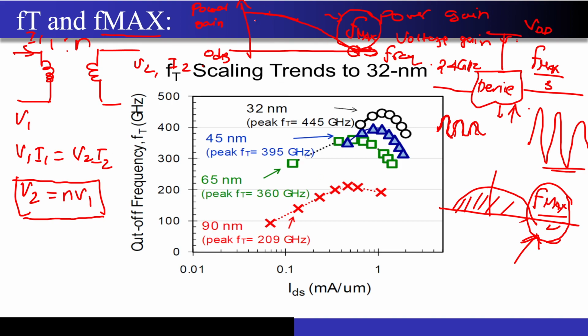Power gain, we usually want a very high number, right? For example, if I get 30 dB of power gain from this device, that is even better, because I can get a lot of swing from here, correct? But if this power gain is just around maybe 5 dB or something, then this is not sufficient for pumping out enough power if I want to send a signal from mobile to base station, correct?